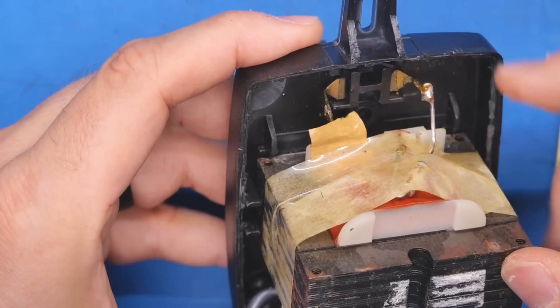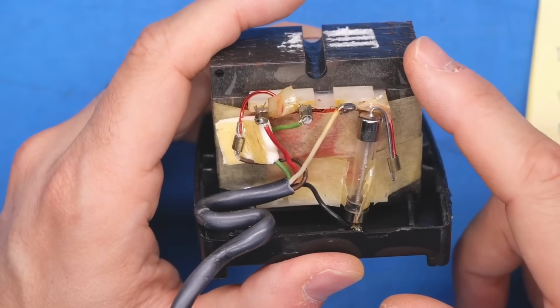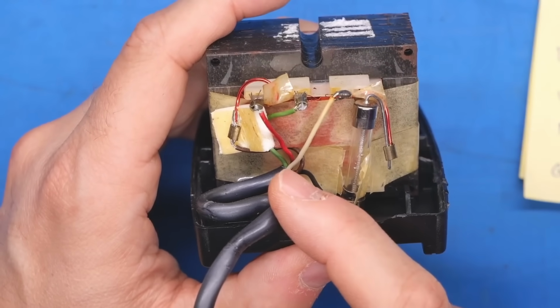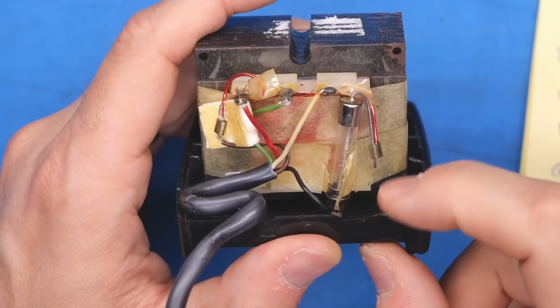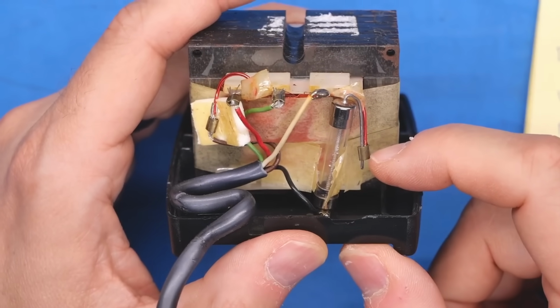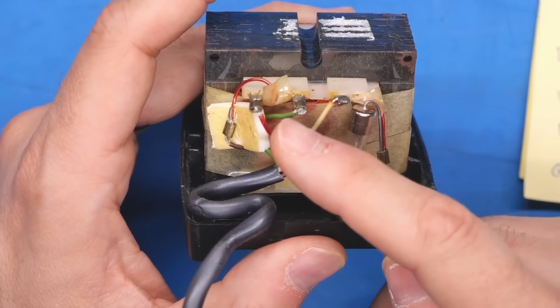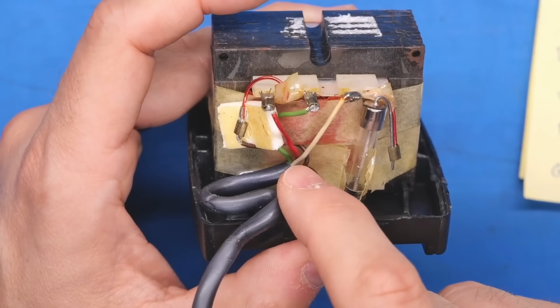So taking a closer look, this is the primary side, 120 volts mains input. And on the secondary side, the cable that goes to the computer actually has 5 wires. We have red, green, white, brown, and black. We can see that the black wire is the one that's attached to the bottom of the fuse, and then that goes to this winding. It's crimped on. And you'll notice this winding comes out of the power supply, and it's not on one of the tabs. Well, its matching winding is this one, most likely, and that's the brown wire.